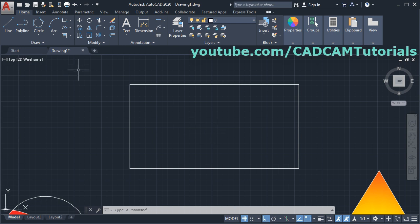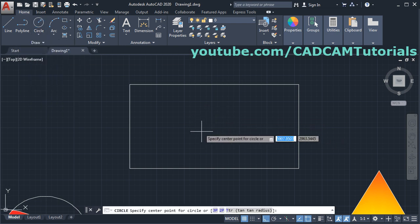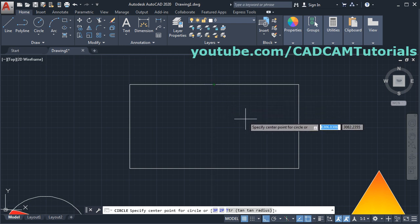Click on circle. Now this center point will be in line with this midpoint and this midpoint. So take your cursor to this midpoint. Don't click there. Hold it for some time and take it away. You can see that a green plus sign is created. So it is ready for tracking.